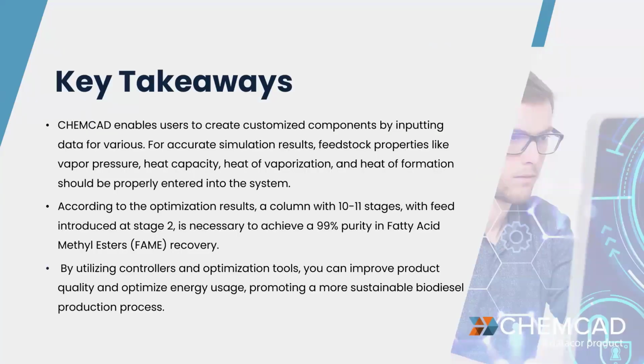So this brings us to the point where we can summarize the key takeaways from the presentation. CHEMCAD enables users to create customized components in case you need it by inputting data from various sources for accurate simulation results. Feedstock properties like vapor pressure, heat capacity, heat of vaporization, heat of formation, you should properly enter those into the system.